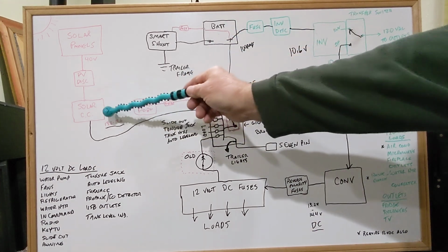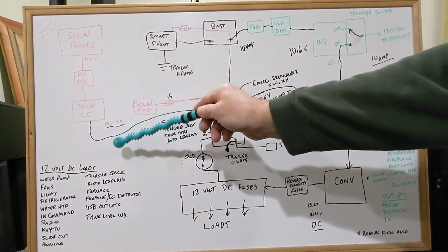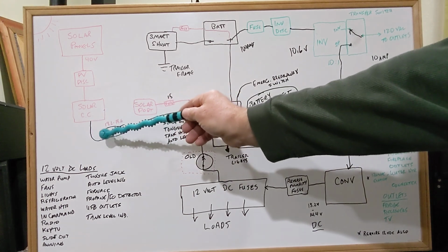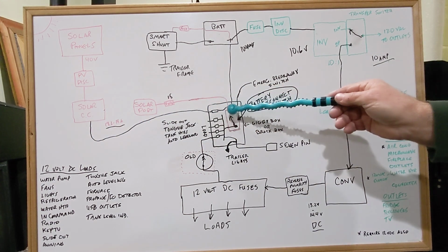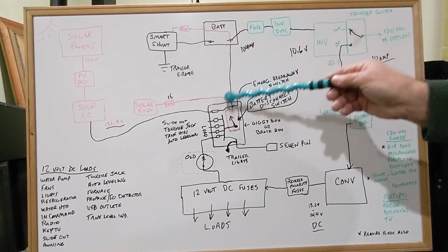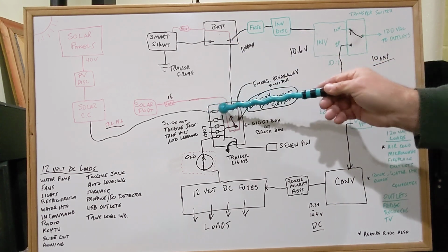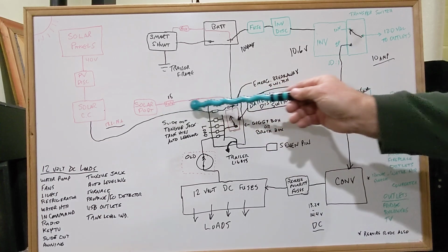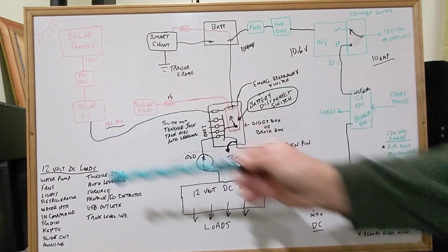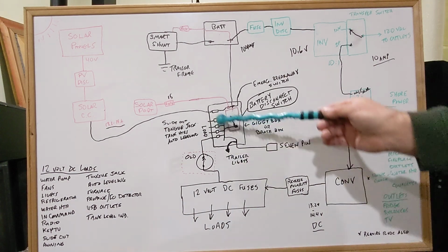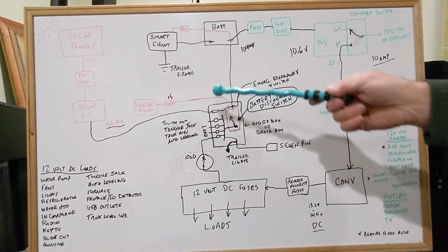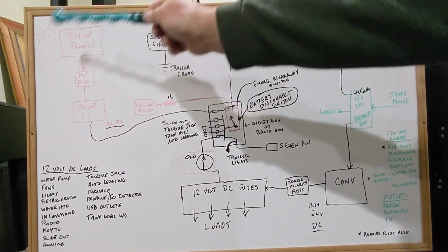You want to check those and make sure you have the right settings in there so it's charging properly. So the power comes out of the charge controller, comes over here into your Giggy box through a circuit breaker, and it connects into there. And like I said, it's always charging the battery. There's actually no way to disconnect the output of the charge controller except for disconnecting the wires at the charge controller. So that's your solar. It's always doing its thing.